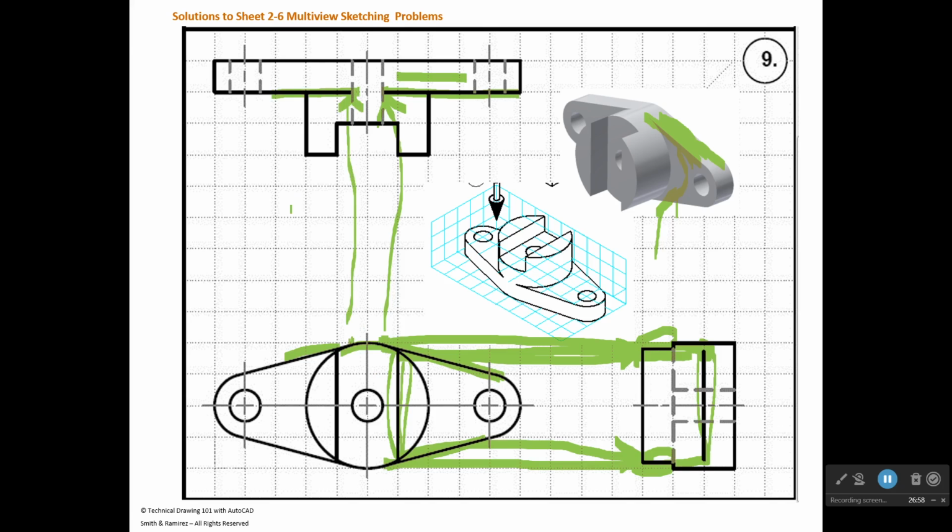And in the parts that we're going to draw with AutoCAD in the next couple of classes, we're going to have a situation like this where we have an inclined plane running up onto a cylinder, and you're going to have to end that run out, and so you'll need to project from the tangent point in the front view up to the top view and over to the side views to figure it out.